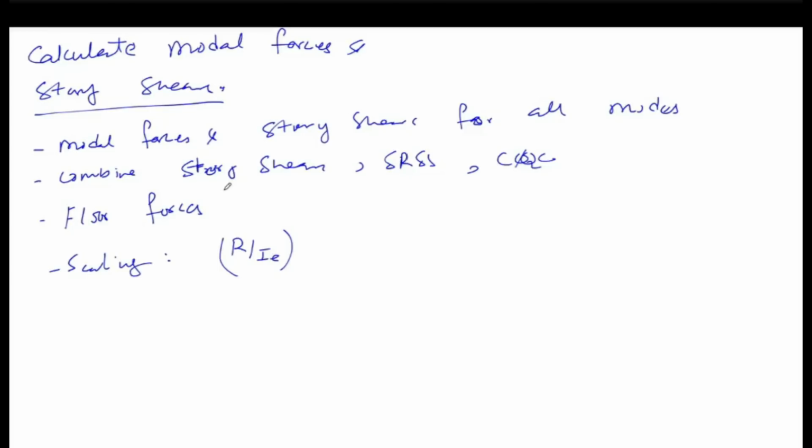And also, for the scaling, we have to note V dynamic, the base shear obtained through modal response spectrum analysis, which we call V dynamic.